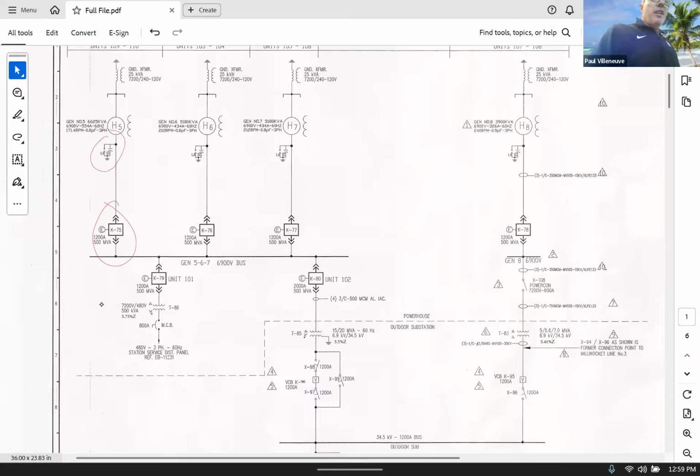These devices over here, a little hard to see. Those are called lightning arresters or surge capacitors. They're kind of 2 different pieces of equipment, but they essentially do the same thing. And the idea is they provide protection for the generators in the event of a surge from either lightning or switching. So under normal conditions, are those in operation? Are they actually functioning? They better not be, because that means you're experiencing surges, right?